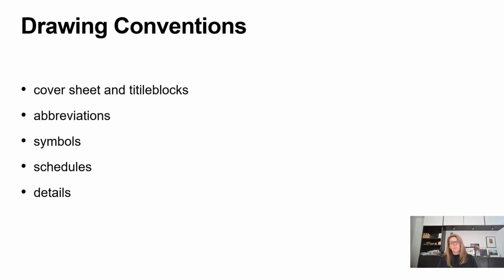And then internal to each one of those disciplines, there will be information associated with the architectural drawings, the plumbing, etc. There's a pretty standard set of abbreviations that are used. Typically in our drawing sets, those abbreviations would be noted generally on the second sheet in a project so that everybody's clear what those abbreviations stand for. It again helps to keep the drawing set as clean as possible, and then how to read the symbols that are also used on that.